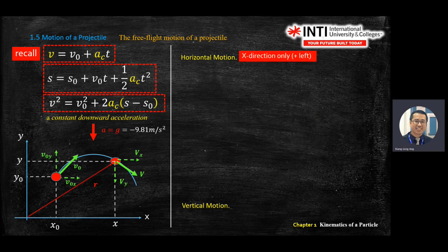So I will show you how to do it. In this example, I start with the horizontal direction only. So I focus on the X direction. And then I close off all the vertical direction. To do this, make sure you convert all the resultant vectors, either acceleration or velocity, into X and Y axis, right? So in this case, all the X to the right is positive.